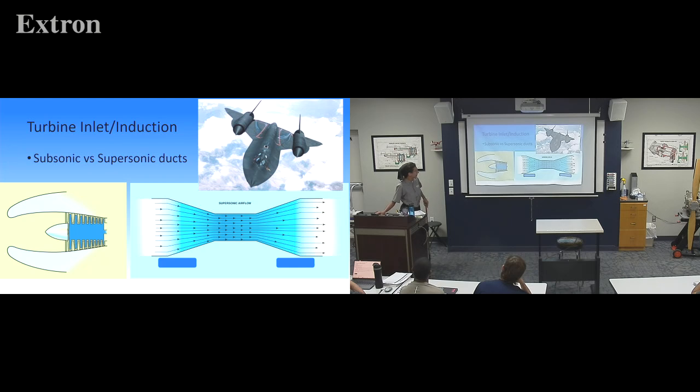So here is supersonic airflow. So now exactly what Leo said, it'll be opposite. Velocity decreasing, pressure increasing on supersonic, and then velocity increasing, pressure decreasing. So what do we do with inlets on really cool jet aircraft?